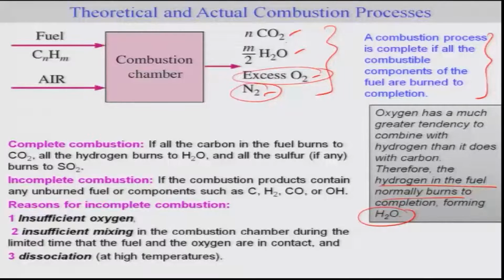Let me just go through the definition of complete and incomplete combustion. Complete combustion is when all the carbon in the fuel burns to CO2, so that means CO2 has to be present, and all the hydrogen burns to H2O, and all the sulfur, if any, burns to SO2. Now we are quite well aware that SO2 and CO2 are not so good for the environment. But this also means that reducing the carbon and sulfur in the fuel is critical to having a better, more environmentally friendly fuel.